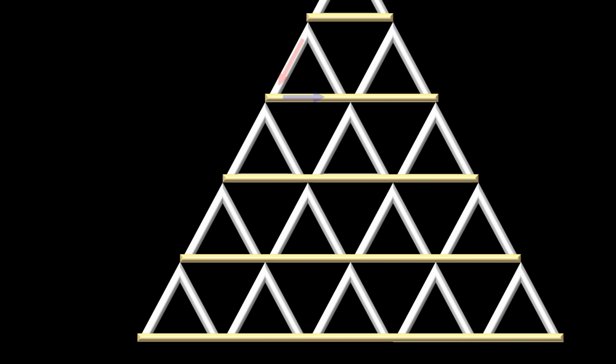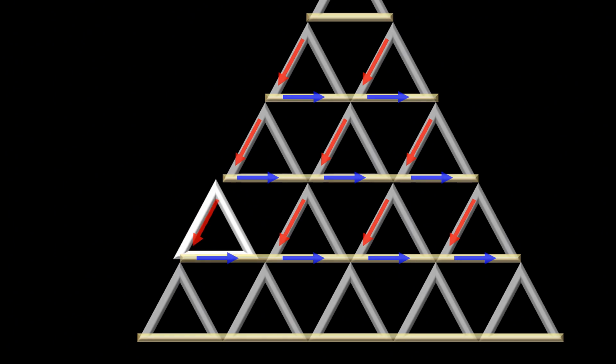A large number of these models are arranged in the diamond grid so they make a structure that holds each other's loads and transmits the load. The resistance to the vertical load is affected by the sine value of the diagonal, and the resistance to the horizontal load is affected by the cosine value of the diagonal. The horizontal and vertical resistance of the diagrid is affected by the angle of the diagrid.